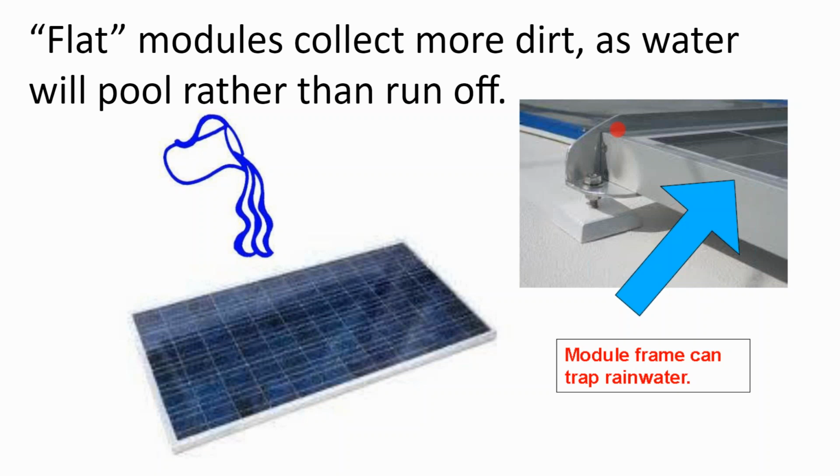So always give your solar panel a good tilt. Even if for whatever reason you determine that the modules should go flat, try and get them a 5-degree tilt. But I really like tilts that are even steeper than that, like on a flat roof where you're doing a commercial install. I wouldn't tilt all the way up to ideal tilt angle. That's too much. The shadows cast from the panels will take up too much space. But even still, going with a 10 or a 15-degree tilt is good, and you'll still get gunk and accumulation on a 10-degree tilt. On a residential roof at a steeper tilt, you might get less gunk on the panel because you have a more vigorous runoff than your rainwater runoff on your flat solar panel on your rooftop.